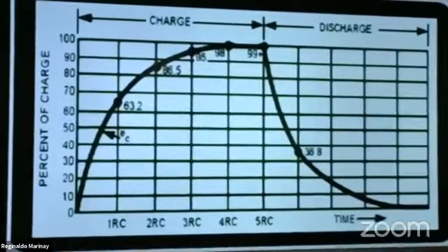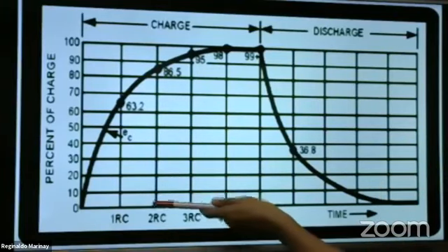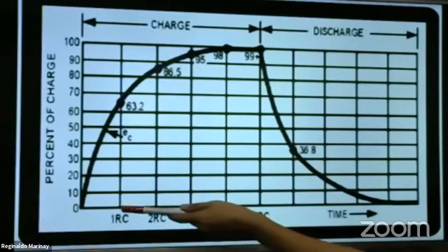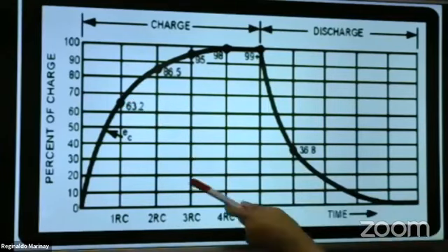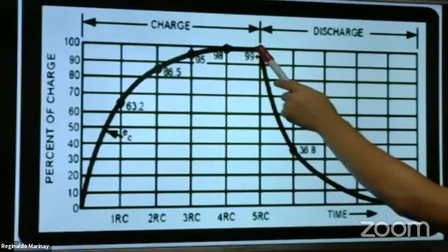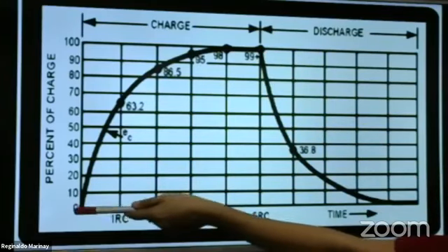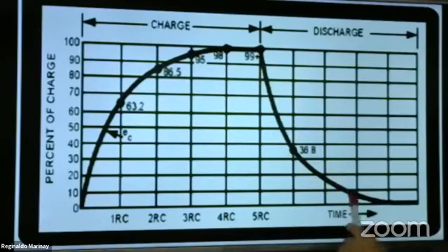Okay, let us go over this with our PowerPoint. So the time constant for RC is also the time it takes to reach 63.2% of the steady state value. So when you reach 5 time constants, no, then you reach the steady state value. So this is what we call the charging process for the capacitor, and we have the discharging process. This decay portion is the discharging process for the capacitor, no?